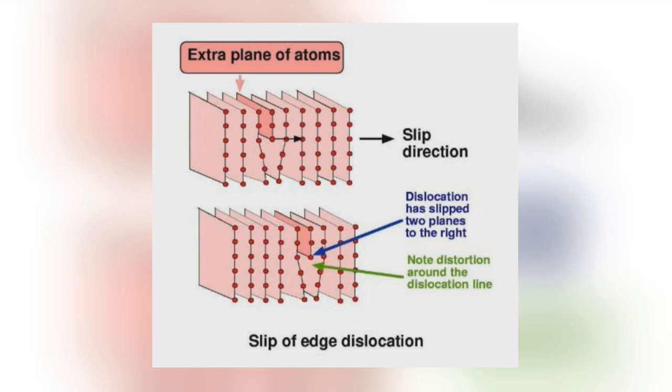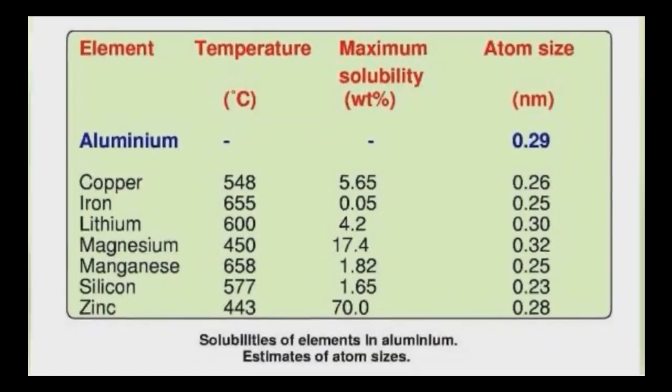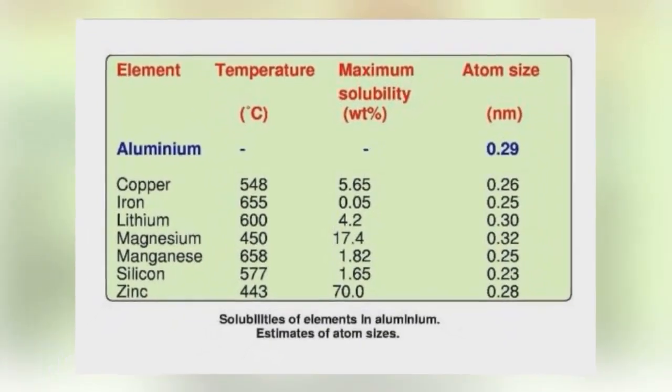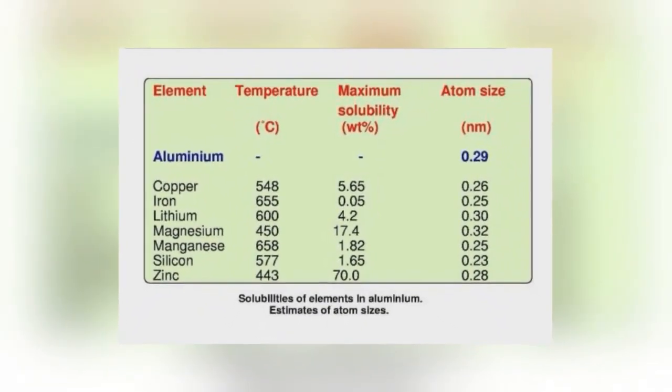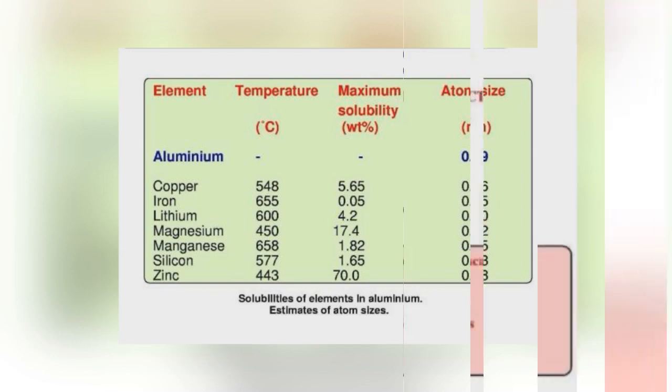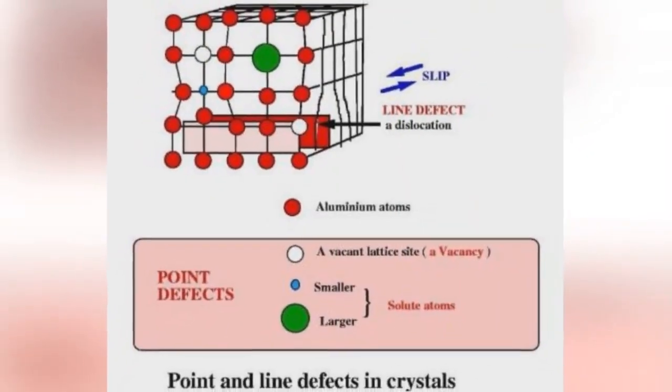In commercial applications, aluminium usually contains impurities like iron and silicon. These impurities lead to the formation of insoluble particles, impacting material properties. Alloying elements like copper and magnesium dissolve in aluminium, distorting the lattice and influencing its responses to mechanical and thermal treatments. In a solid solution, the foreign atom substitutes for an aluminium atom.